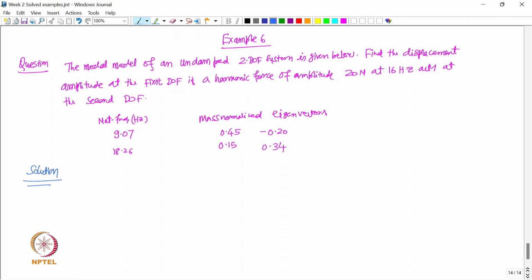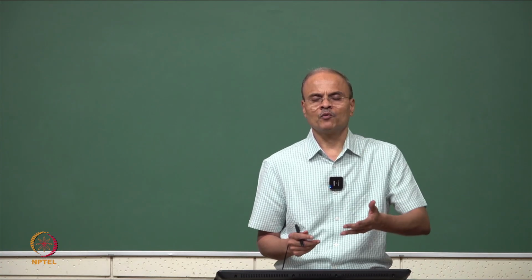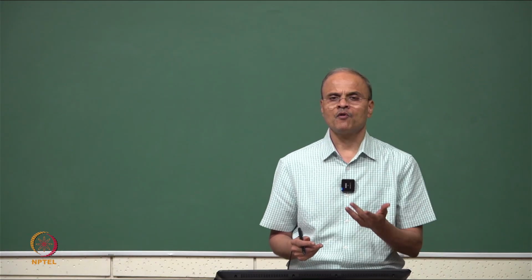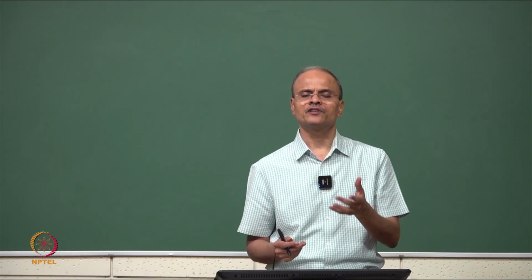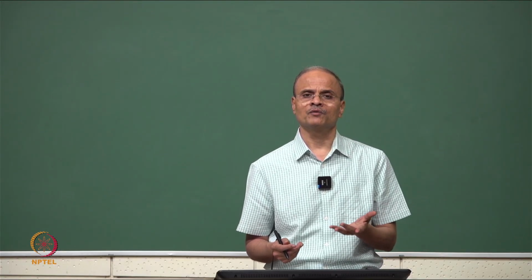So you can see in this case, we are supposed to identify the response of the structure due to a force acting at some degree of freedom, using the information about the model of the system. A modal model can also be identified experimentally, as we are learning in this course through modal testing. If such information is available, then that also can be used to predict the response at different points on the structure, and that is the strength and advantage of the modal model.